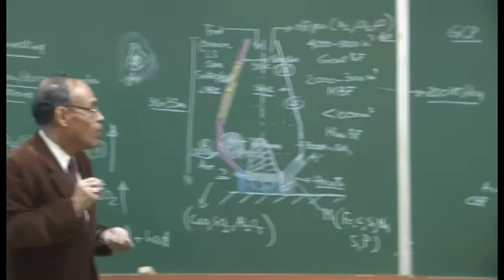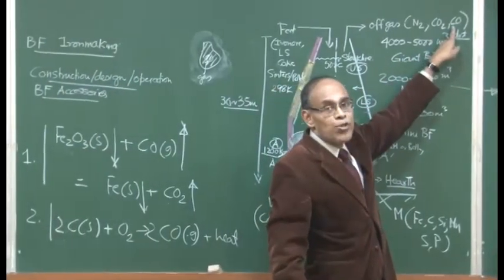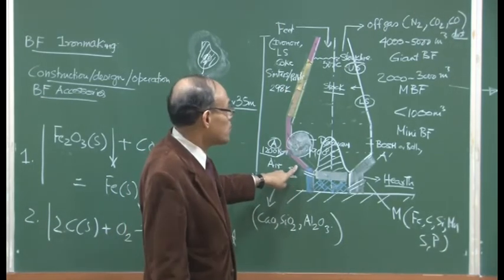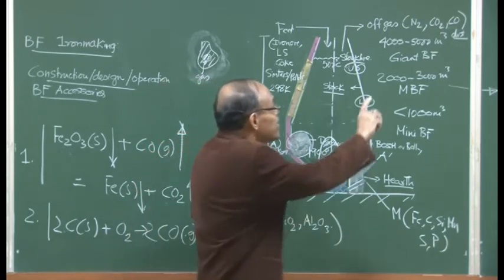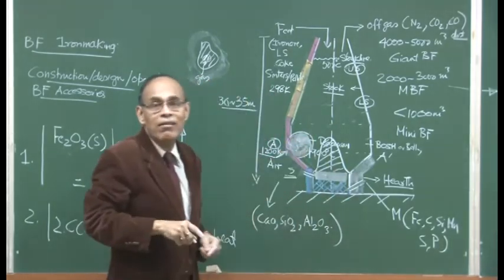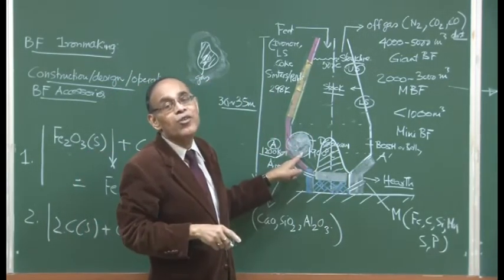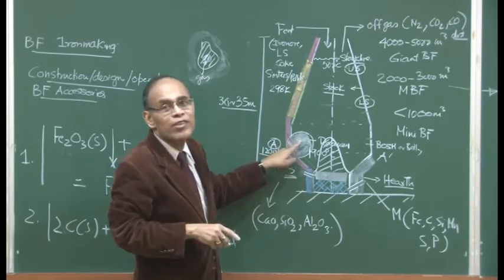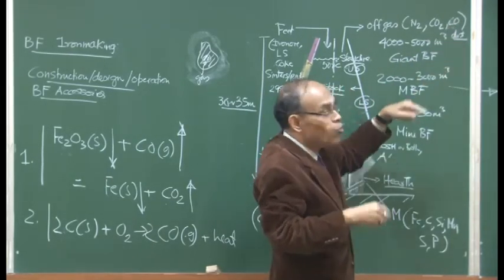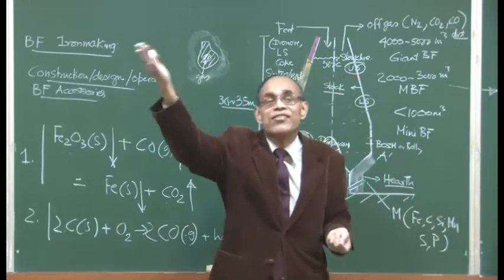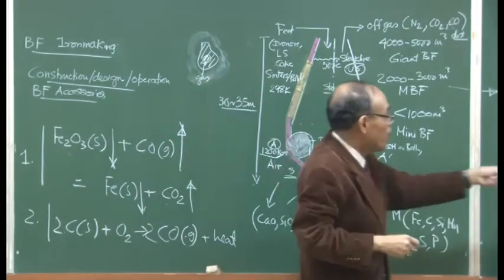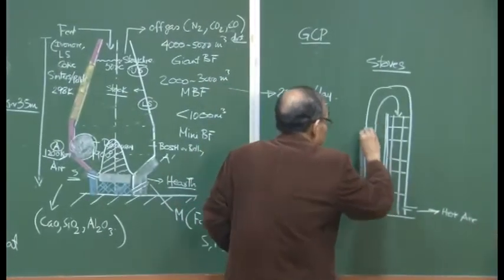as a result of which this carbon monoxide has been produced by burning coke within the blast furnace, and coke is substantially more expensive than coal. So, by recycling the chemical heat contained in carbon monoxide, we in turn have been able to save a part of the coke that we have charged into the furnace itself. If we use this carbon monoxide to combust and run, for example, the light or the fan in this room, it is not efficient usage, but this supply of heat back into the furnace via the stoves is a very important step in iron making.